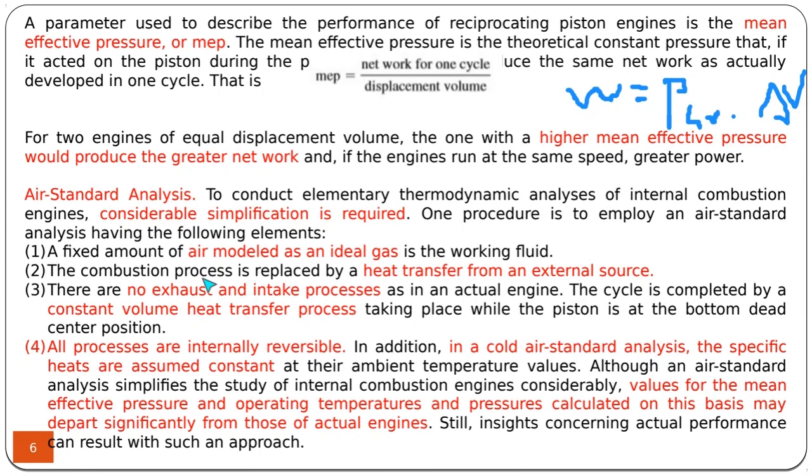In order to analyze the internal combustion engines, the reciprocating engines, we use two different approaches. One of them is air standard analysis. According to air standard analysis, the air or the gas inside the cylinder is assumed to be an ideal gas because the fraction of the fuel is much smaller than the fraction of the air. That's why we can assume that it's comprised of pure air.